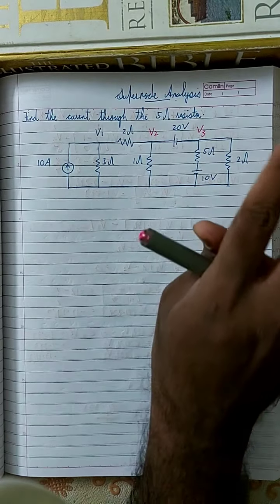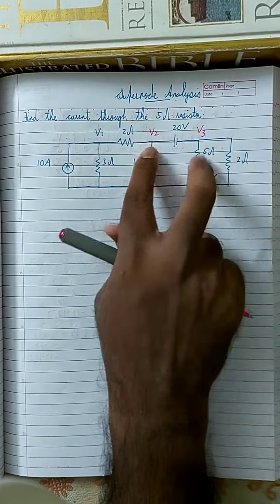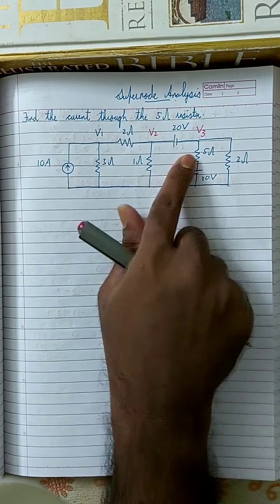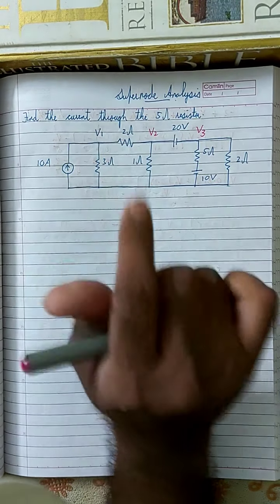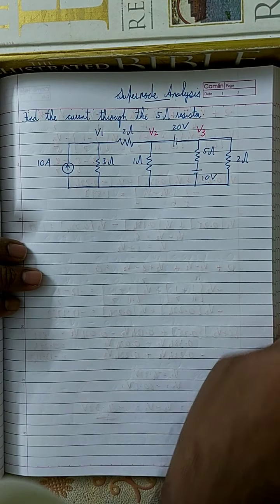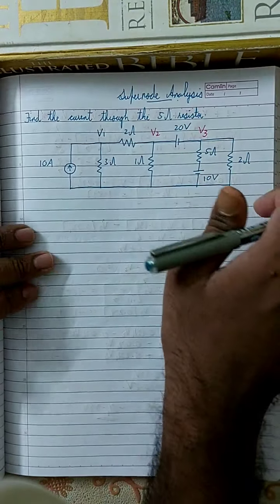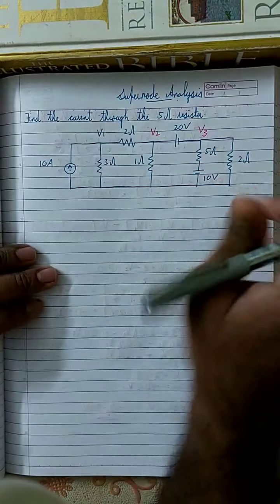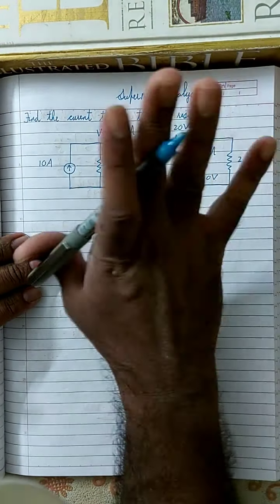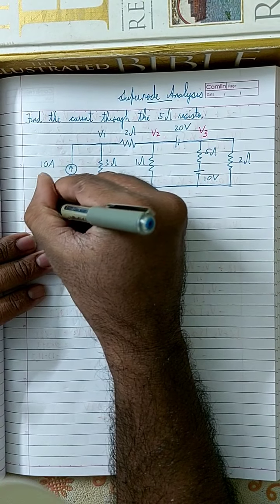Okay, so anytime, if you see two nodes combined by a voltage source, immediately you have to apply supernode analysis. So what do you mean by supernode analysis is because just look how we do this problem. Here I am going to apply the equation for node V1. Alright, as usual, standard, there is not much change, right? Everything is just the same. So equation